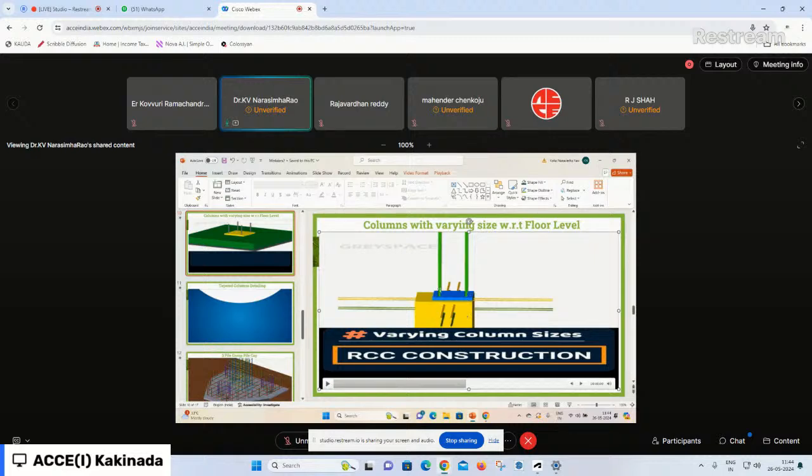We anyhow provide new bars due to the curtailment, and these should be at least side bars from the bottom bars, so that the 50% curtailment condition can be satisfied very effectively. That is, the bottom bars should have a continuation, and the new bars meet the requirements of the reduced column size. That is important.